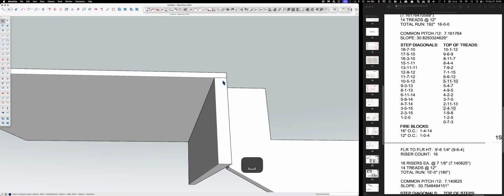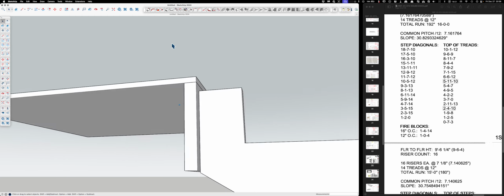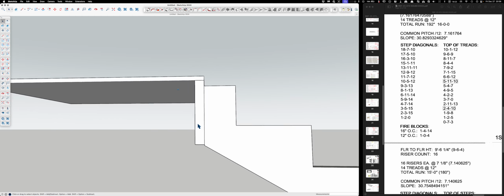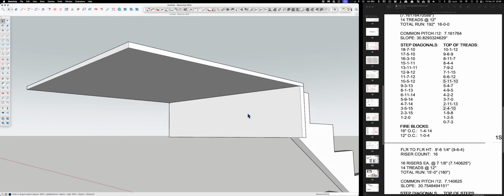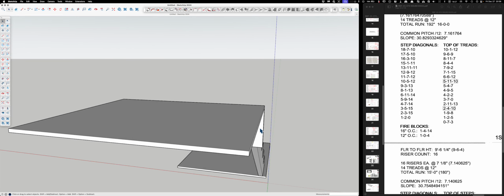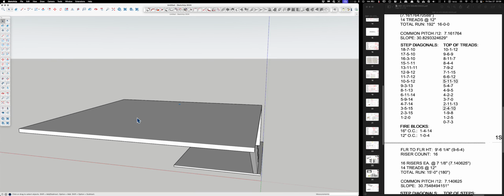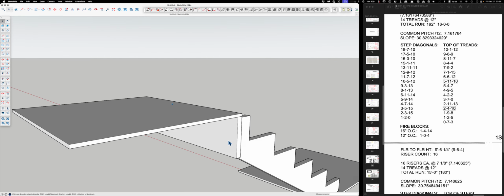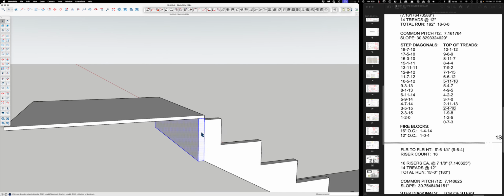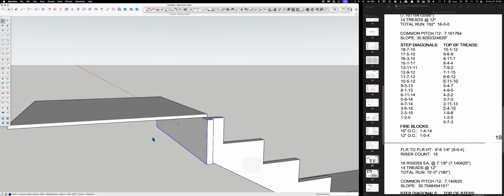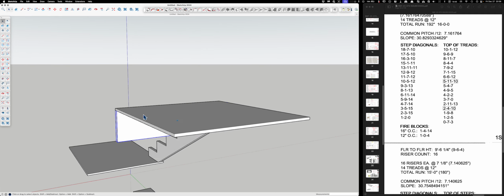You don't have to use. Yeah, look at that. Look how much of the stairs is supported by this. I run this into the wall. Like there's a wall right along here, and the platform is tight against the wall, and then I will extend this into the wall. So I would go like 3.5 or whatever the wall thickness is. And then I would double it, and I'll box that out in just a little bit.